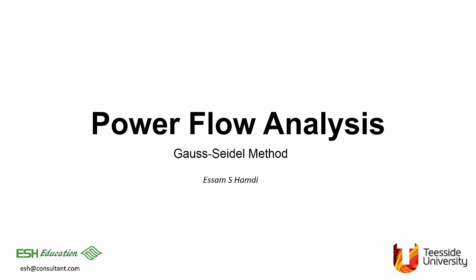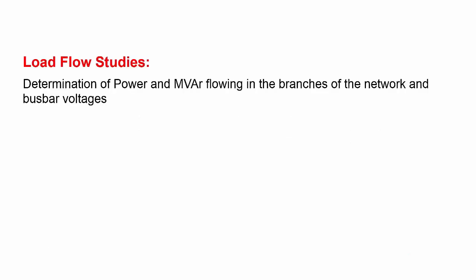Hello everyone. In this part I'm going to introduce the power flow analysis. What do we mean by power flow analysis? Power flow studies consist of calculating the voltages, that's magnitude and angle, at each node or bus bar of the network, and the real and reactive power. Of course, if we know the voltages, we can calculate the real power P and reactive power Q.